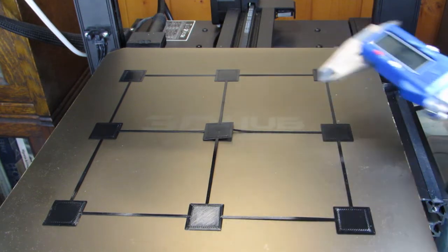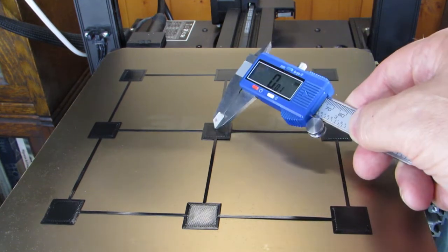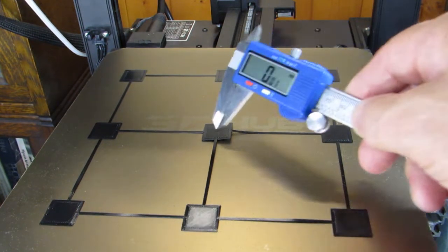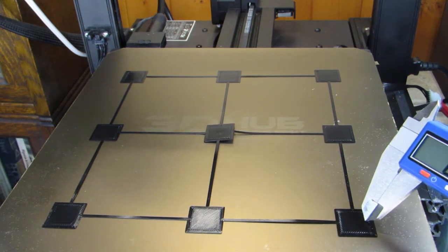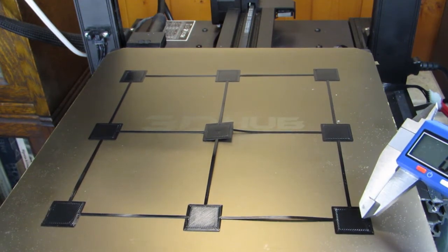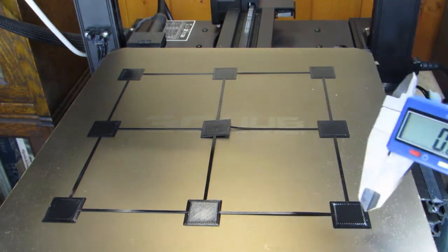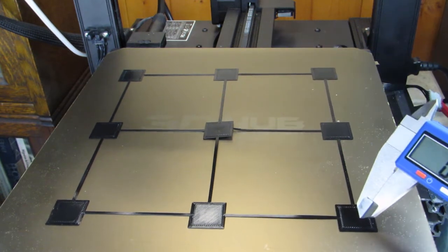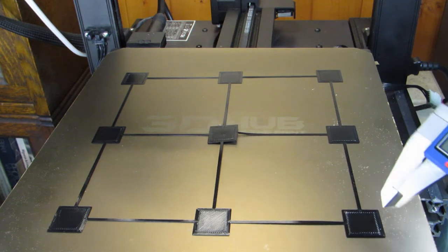I think there's an accumulation of errors here also between homing and the probing of each point. Both of those could be off by 0.01, which is 0.02 worst case stacked against me, or cancelled out if it goes t'other way for me. If the hysteresis was 0.02 at the time, then that would account completely for the 0.04 error in this term.